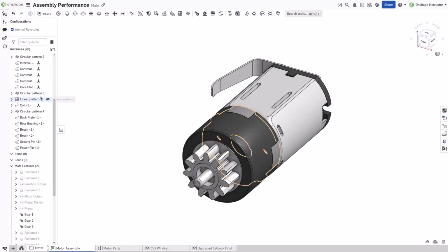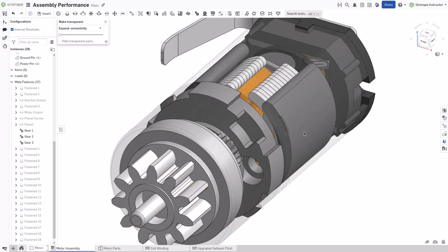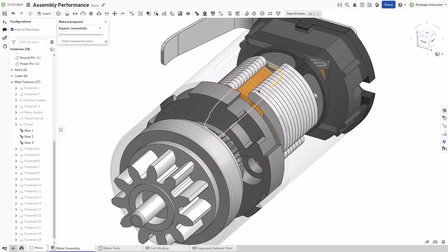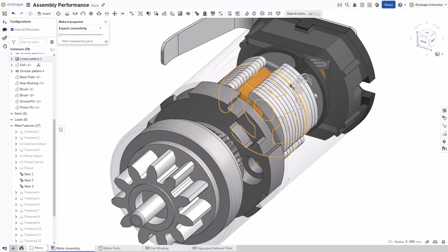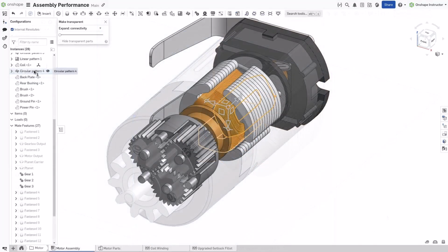The structure and appearance of an assembly are paramount to improving performance and workflow in a document. It is strongly recommended to instance parts in an assembly, not a part studio. Instancing in the part studio creates discrete parts with unique IDs. Assemblies render multiple instances of the same component faster than separate components. Even if they are geometrically identical, the assembly interprets them as distinct components.